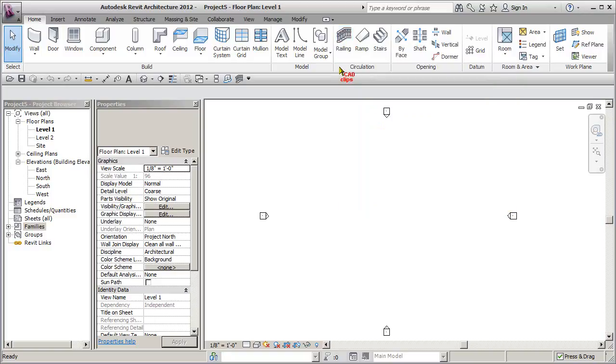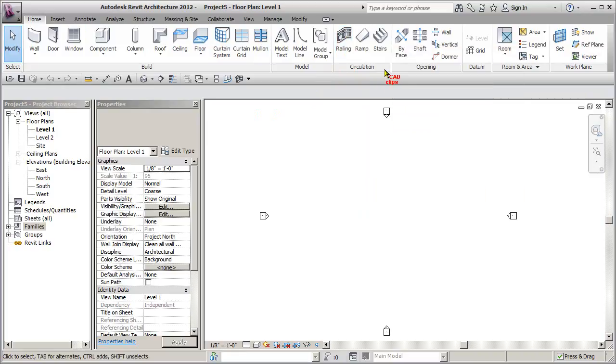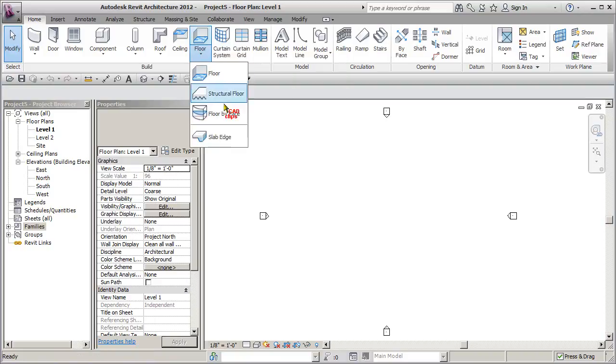Okay, and on that note, you'll notice that this is what is called a tab. This is what is called a tool. These are individual tools. And the individual areas here with the lines vertically are panels. This is all the ribbon, but we have a tab, we have a panel, look, the build panel, and then we have the tool. And then sometimes the tool even has a flyout on top of that.